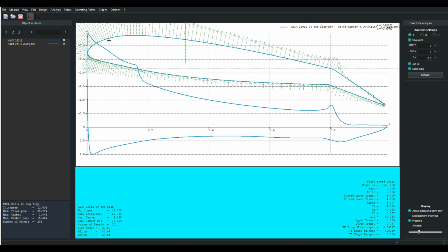Well, here it's a little bit better because we sped them up even more up front, so the flow here on the leading edge of the wing is even faster. Those molecules have a little bit more inertia to get through this pressure gradient. So they're going along, doop, doop, doop. We're doing the job. We're going into the adverse pressure gradient. They're losing velocity, but they're going, I'll make it. Don't worry. I'll get back to my nominal conditions.